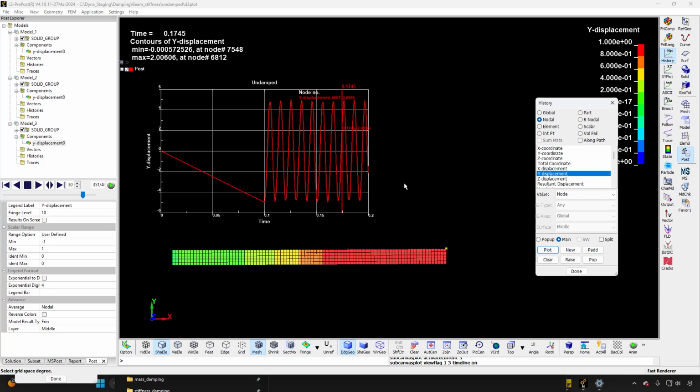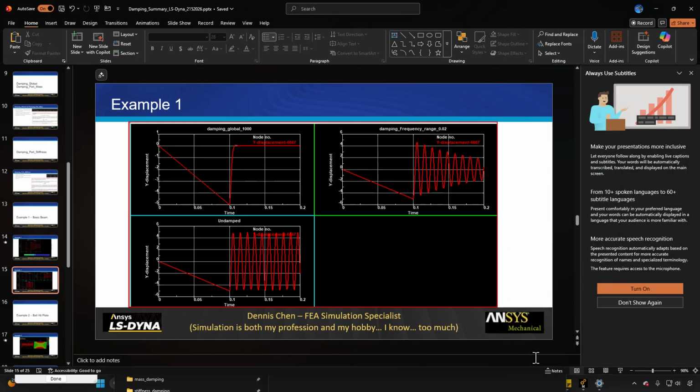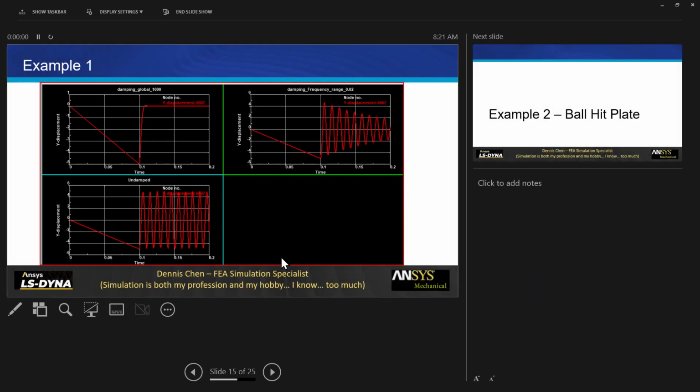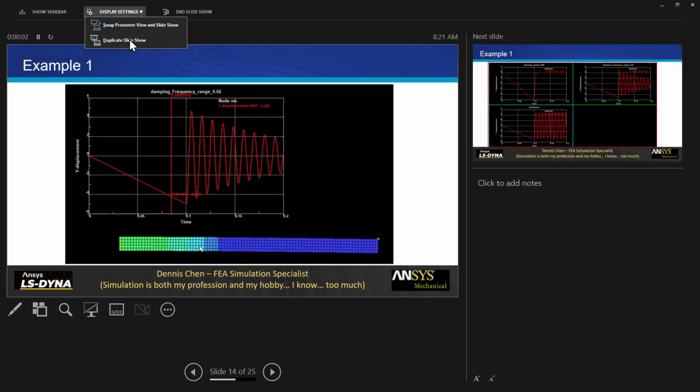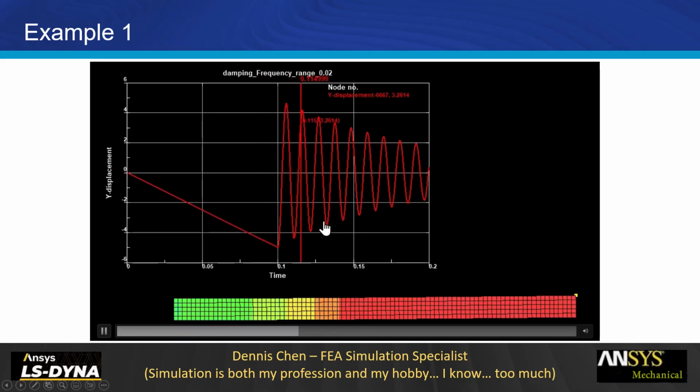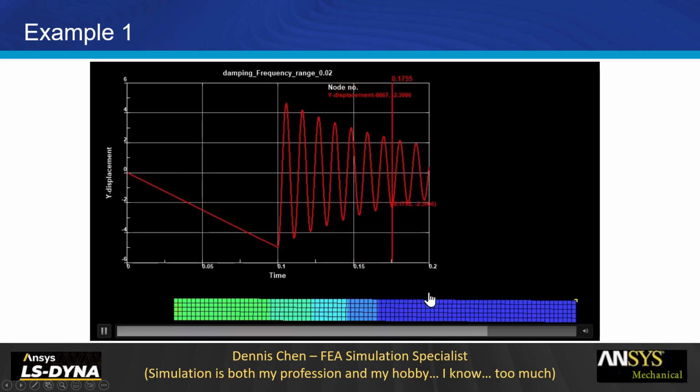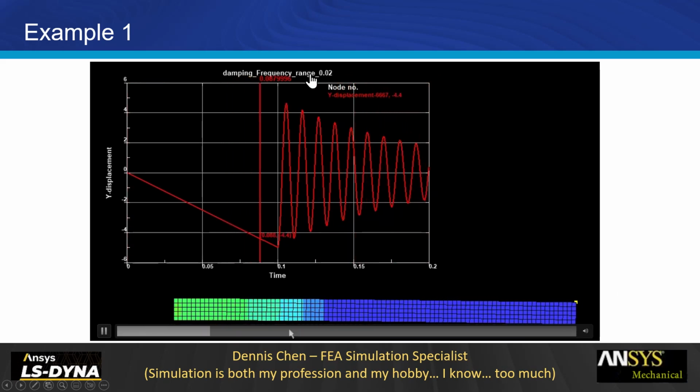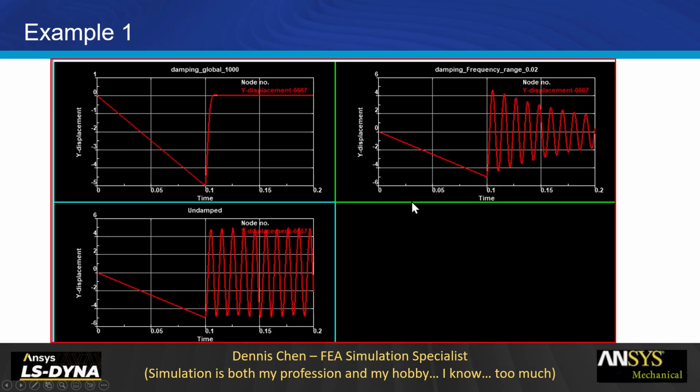That's a very standard type of problem that we can look at. Basically, it depends on the amount of damping you add. You adjust the dynamic stiffness of the system, but it also allows you to apply a certain amount of damping. So for a problem like these, right, you can just apply stiffness-based damping, or even apply mass-based damping, as long as the number is adequate. You don't over-damp it, and we're okay. And you can see we get the same amount of overall deformation under the same amount of load. So it gives you the relatively correct response over time.